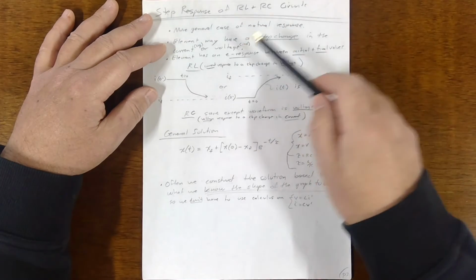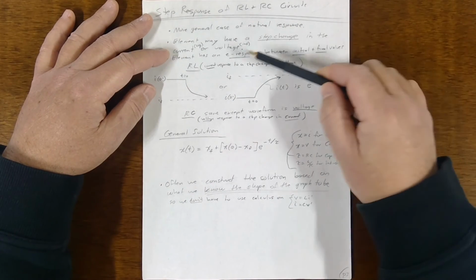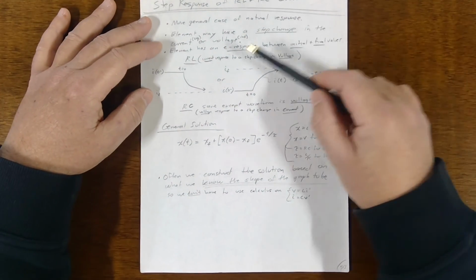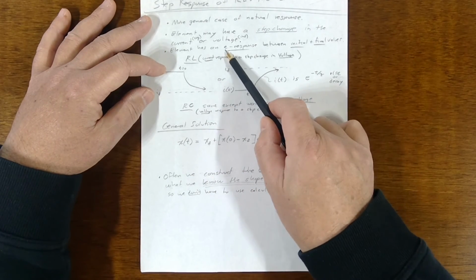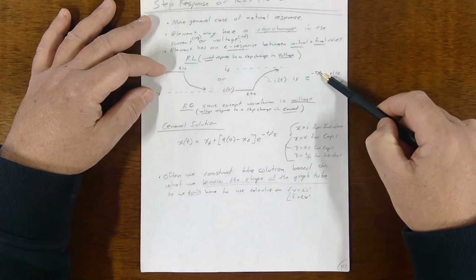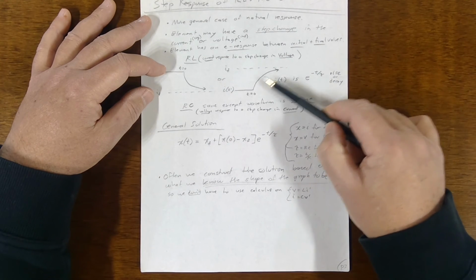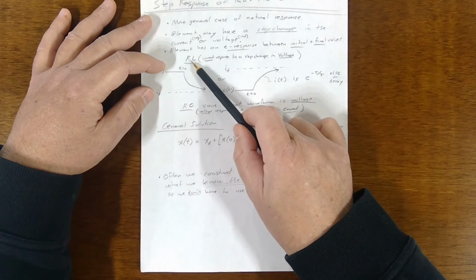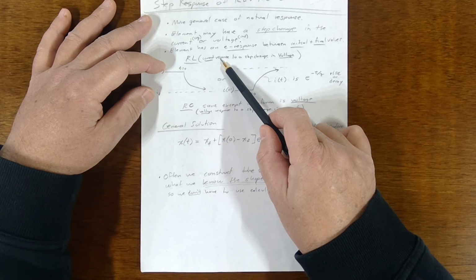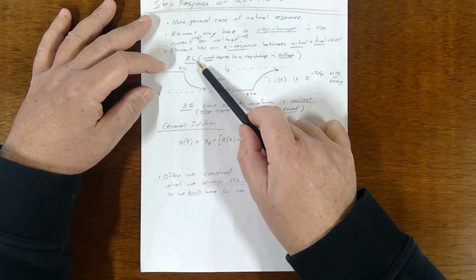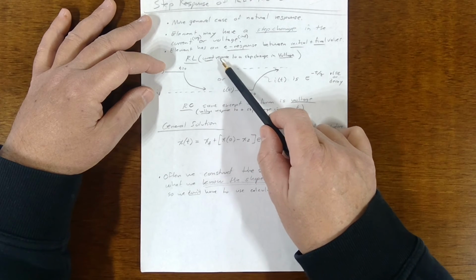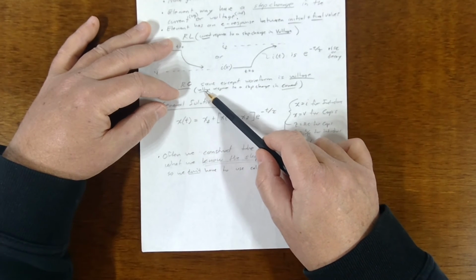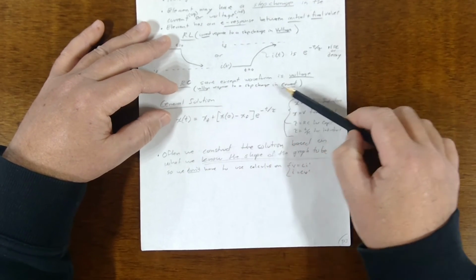All right, so keep in mind that an element may have a step change in the current for a cap or the voltage for an inductor. And so there's an initial state and a final state, and there's what I call an e response, this e to the minus t by tau response between the initial and the final state. For an RL circuit, we will be solving for the current response to a step change in voltage. And for an RC circuit, we will be solving for the voltage response to a step change in current.